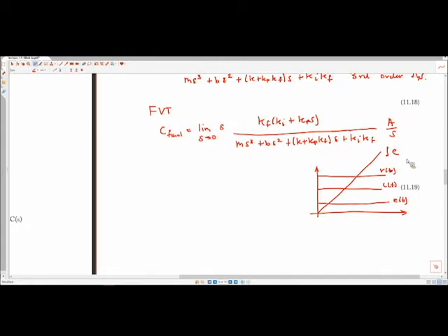We'll talk about some of the more basic problems with it, and the fact that we are adding a zero or a pole to the system. Anytime you add a pole to the system, you're making the system a little more prone to going unstable. So it can have negative effects on the stability, besides the point you just described as well. Okay, so definitely some negative effects.